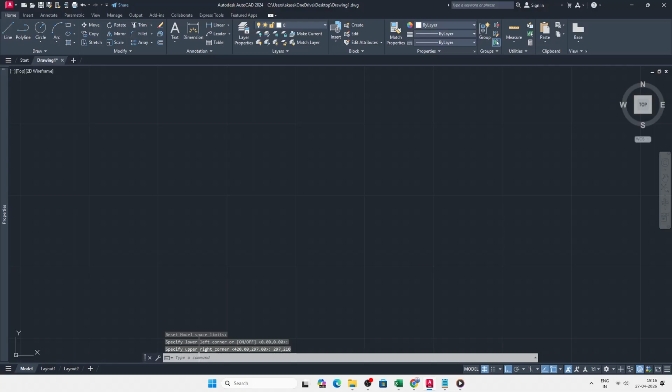Now that the corners are defined, activate the limits. Type limits again, then type on and press enter. Turning limits on tells AutoCAD to honor that boundary when navigating. In most modern setups, it won't stop you from placing objects beyond the edge, but it guides how the view behaves and works with zoom. Also, your defined rectangle becomes the visible working canvas.